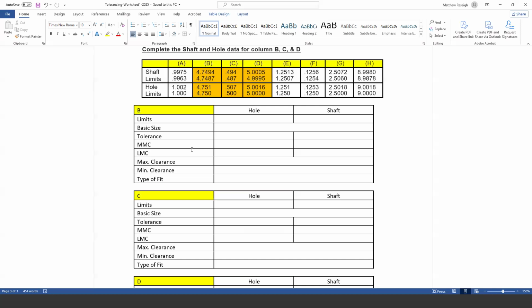But there were cases when we built ours that they'd cut these big chunks of plate. They would heat them up really hot and insert them on the shaft while they were hot and expanded. And then as they contracted, there would be an interference fit. So they can use heat to make an interference fit slide together.